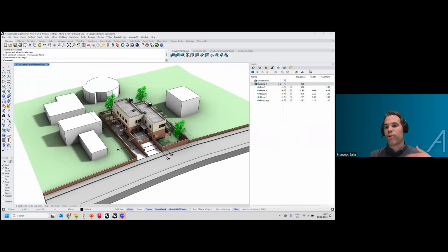Now imagine a situation where we have more than one building. So we can create new buildings from this icon. Each building can be at a specific level. That means that we can have this level at 1 meter. Also, we can visualize these. All the levels contained in a building have the elevation in relation to the building's elevation. But now we can see this elevation in relation to the building's elevation or to the global coordinates. And we can toggle this option from here. Okay, now it's global, and if we unclick, it's related to the building. But sorry, the other way around. Okay, now it's related to the global coordinates. If we click here, it's related to the building.